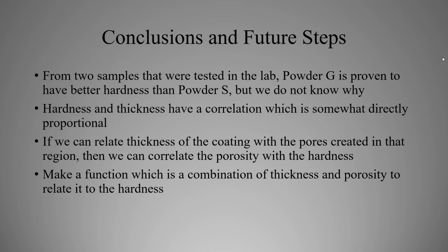If we can relate thickness of the coating with the pores created in the region, then we can correlate the porosity with the hardness. We can attempt to do this by making a function which is a combination of thickness and porosity and then relate it to the hardness values.